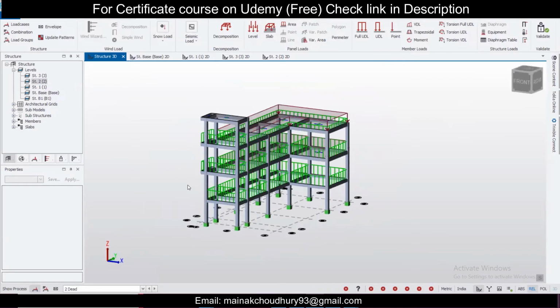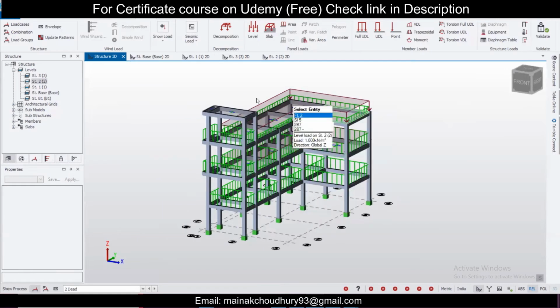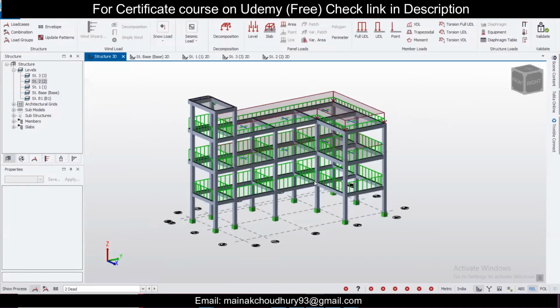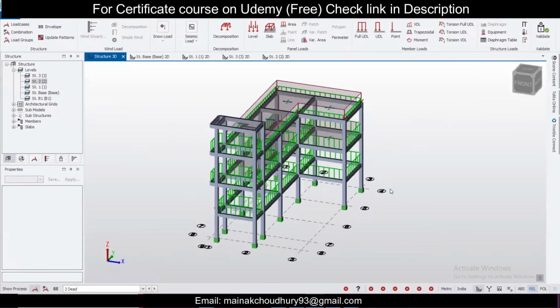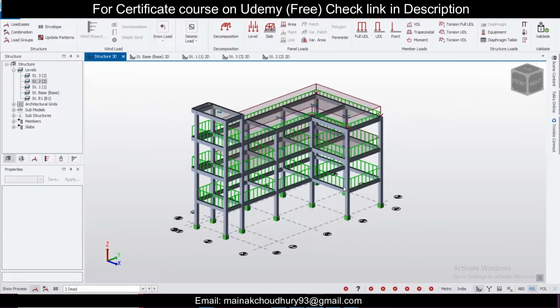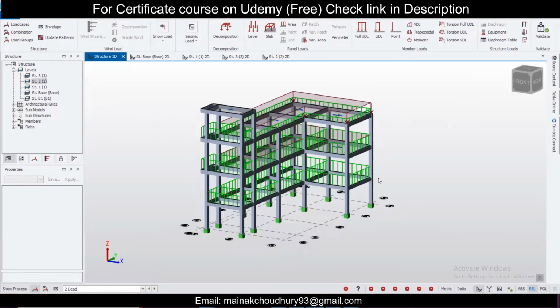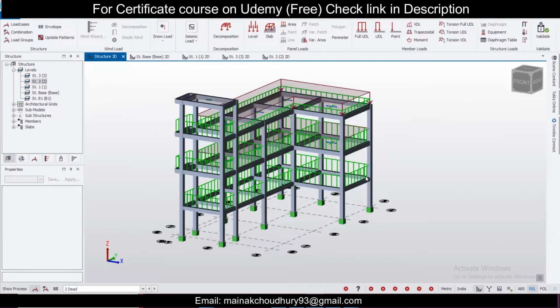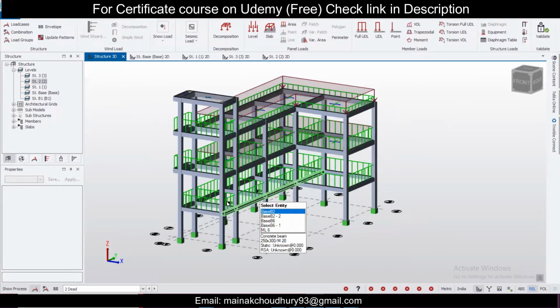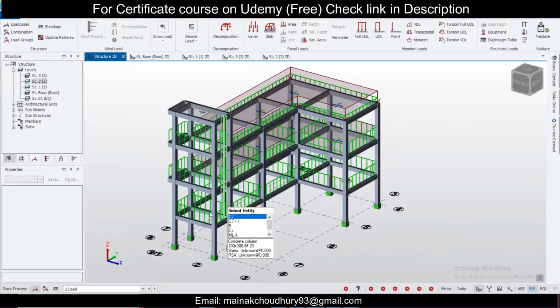So both are important for me, right? Okay. And next part is the live load. And so, what does IS 875 part 2 say? Part 1 and part 2 cover dead load and live load. So part 2 is for the live load. The live load code says that for residential buildings in normal areas, you can apply a live load of 2, and for the staircase and corridors, you can apply a live load of 3.